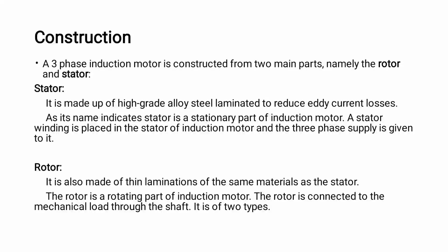Then construction of three-phase induction motor. A three-phase induction motor has two main parts. They are the stator and the rotor. Stator, as the name indicates, is the stationary part of the induction motor. It is made up of high-grade alloy steel, and this is laminated to reduce the eddy current losses.